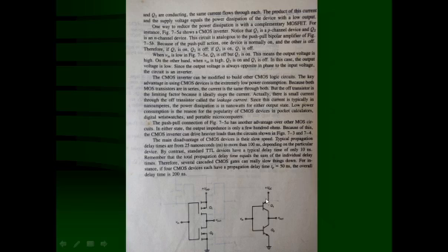You have studied the complementary push-pull amplifier, right? In that case, the PNP transistor is the upper transistor and the NPN transistor is the lower transistor. This emitter is connected with the positive terminal of the battery, and this emitter is connected with the negative terminal of the battery. The two collectors are common, and that will be the output. Here also, the two drains are common, and that is going to be Vout. This way the P-channel as well as the N-channel MOSFET are connected.